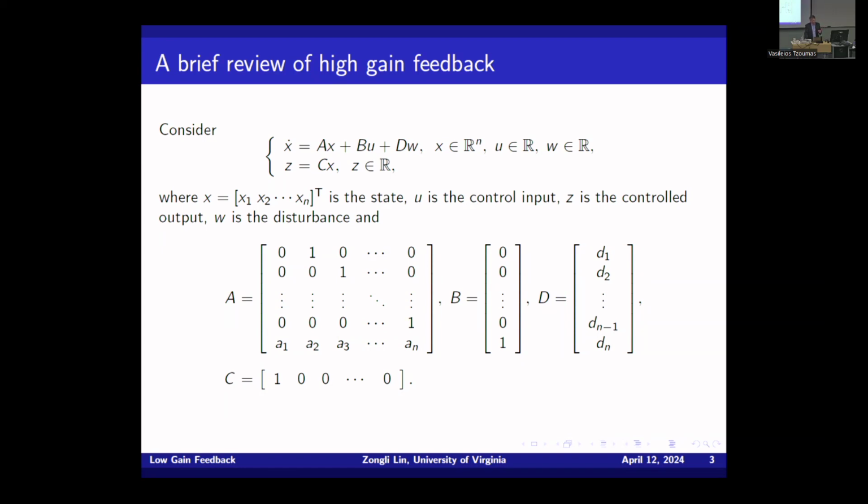It's constant 1. And if you're familiar with this, if you look at the transfer function from u to z here, the numerator is 1. Because the C matrix here, for a single input system, is a vector, right? It's the coefficients of the numerator polynomial, right? Now, if the numerator polynomial is 1, that means I don't have any zero here.